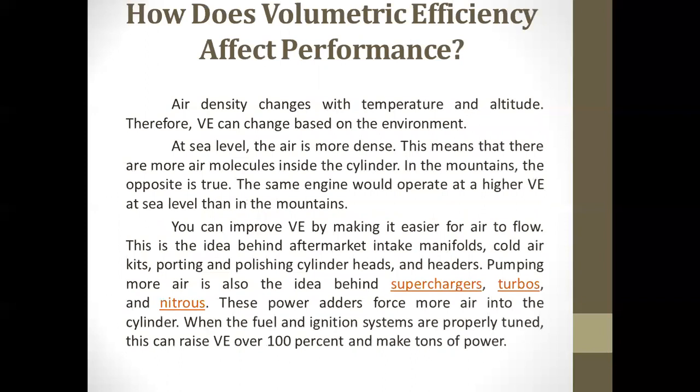How does volumetric efficiency affect performance? Air density changes with temperature and altitude. Therefore, volumetric efficiency can change based on the environment. Hindi lang ginagamit natin ang volumetric efficiency, at hindi lang ito nagbabago sa mga engines pati sa environment natin. At sea level, the air is more dense. This means that there are more air molecules inside the cylinder. In the mountains, the opposite is true. The same engine would operate at a higher volumetric efficiency at sea level than in the mountains.